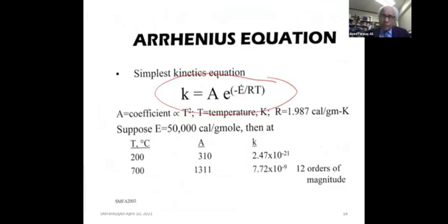Now, in a typical combustion process, there are 13 or 14 or 15 important reactions. Sometimes people narrow them down to 4, and that's why the simulations are not very reliable, and the same goes for the lab tests. The lab tests are good for some parameters, but they won't give you a good number for oil recovery. Do not rely on the oil recovery numbers from either the lab test or from a numerical simulation.